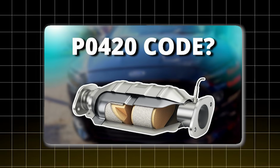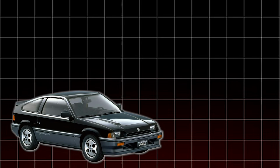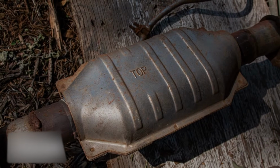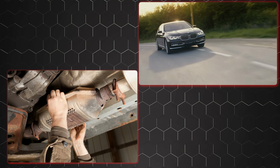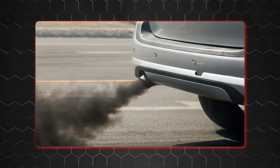Understanding the P0420 code and why it matters. When it comes to maintaining older cars, one common issue that many owners face is the P0420 code, which indicates a problem with the catalytic converter's efficiency. This code is significant because it can lead to decreased vehicle performance, increased emissions, and potential failure during emissions testing.